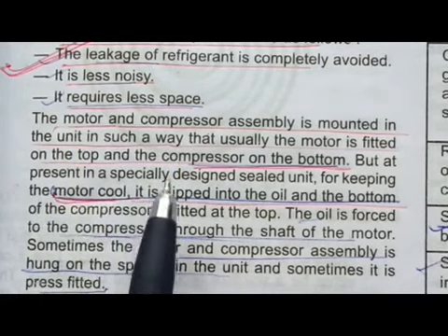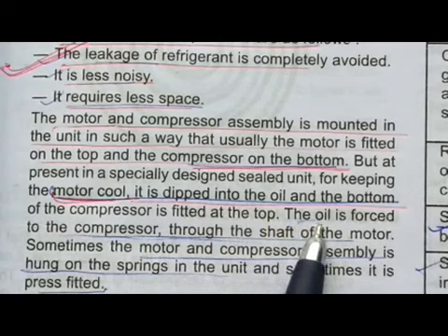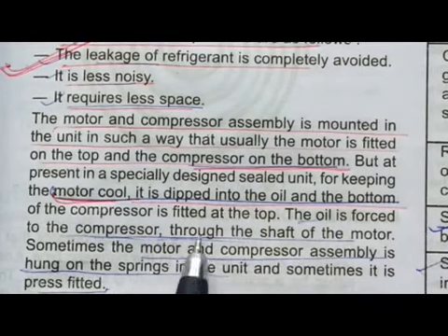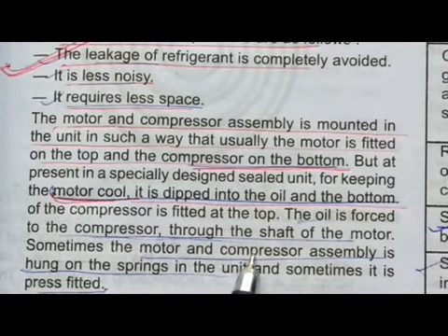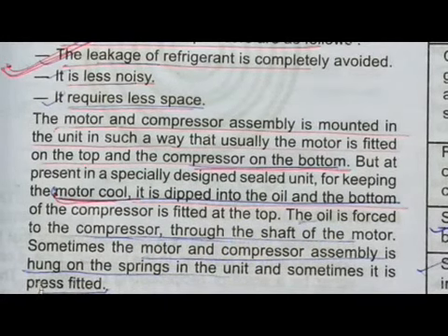The motor is cooled by being dipped into oil, and the bottom of the compressor is fitted at the top. The oil is forced to the compressor through the shaft of the motor. Sometimes the motor and compressor assembly is hung on a spring unit, and sometimes it is press fitted.